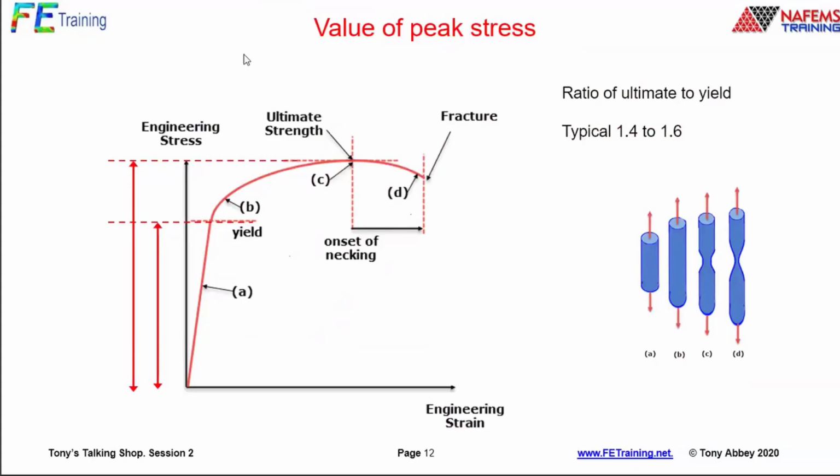And I've seen stress levels reported 6 or 7 times yield stress, which is just physically meaningless. And if you don't make a note of that or mention it, and you actually let that report go out, it's like, well, does the analyst not understand the implications of 6 or 7 times yield, or whatever it is?